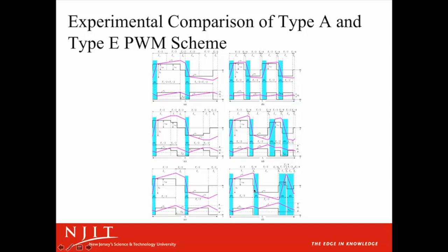As a consequence of these two pulses, they do not contribute any power to the output load and create conduction and switching losses on the primary side. So this was regarding the primary side correlating to the duty cycle loss.